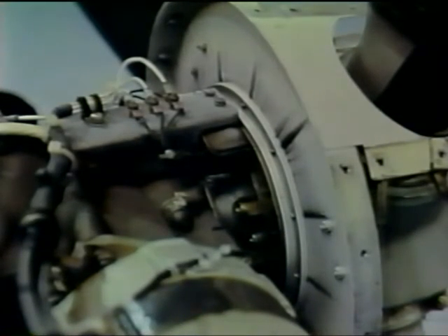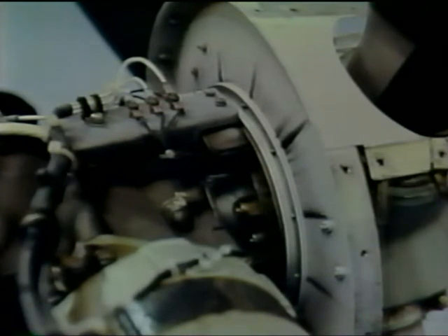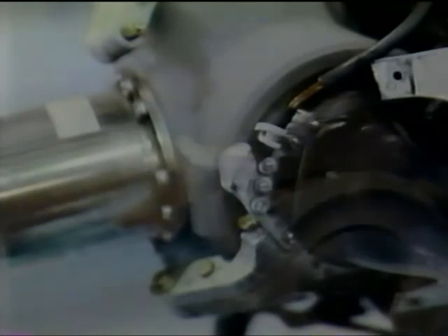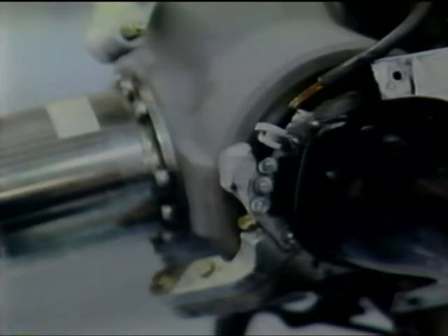Control systems should be checked for defects, improper travel, and improper safety. Lines, hoses, and clamps must be inspected for leaks, improper condition, and looseness. Accessories should be checked for apparent defects in security of mounting. The propeller assembly must be checked for cracks, nicks, binding, and oil leakage, bolts for improper torquing, and lack of safety. Anti-icing and de-icing systems should be checked for improper operation and obvious defects.